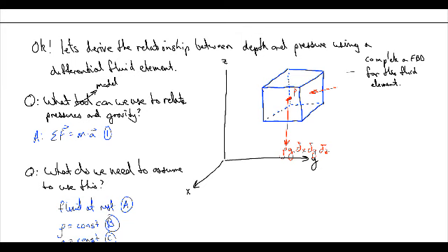So the pressure acting on this face here, we're going to do the y. I kept saying x. We're going to do the y pressure acting in this direction. So we know that the force here is equal to the pressure P, but it's going to change as it goes across this fluid element, right? So we have the pressure in the middle, plus some change in pressure with y, dP/dy. Okay? But that's just the slope. That's just how the pressure is changing across our fluid element.